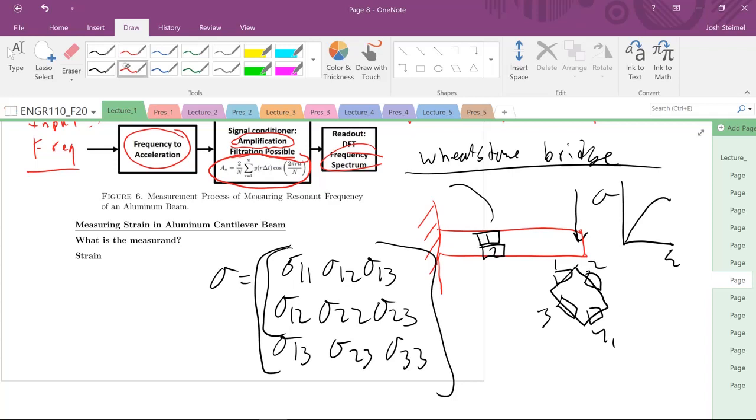But to measure these strains, which are extremely, extremely small, especially for metals, we cannot use our eye. We cannot use a ruler. We need higher resolution. So to do that, we're going to convert our signal, which is this load, this physical strain we're applying to our material, into this Wheatstone bridge electrical signal.